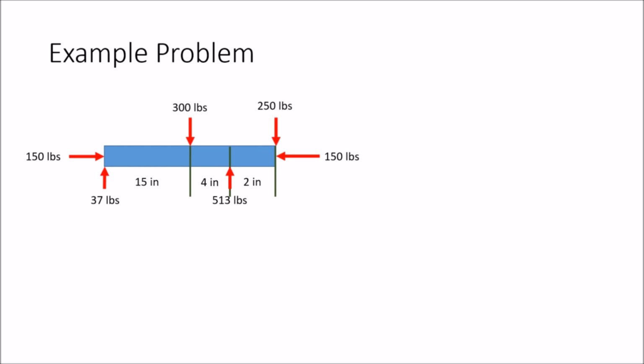Here we will do an example problem of finding the internal reaction forces. Here we have a beam that has the following loadings on it. Since normal force loading doesn't change throughout the entire bar, it will be constant. However, the shear loading changes 3 times, from one end to the other. Those changes mean that we would have different shear forces here, here, and here.